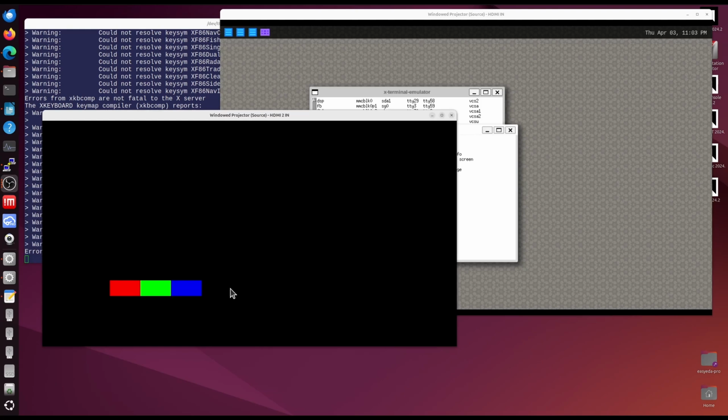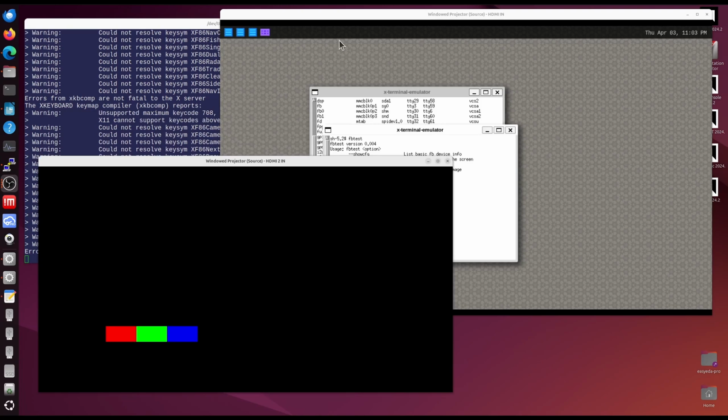And so I'm sure it's a timing thing. It's where's my pixel clock relative to the FIFO, that buffer I've got, or there's something else I haven't quite figured out. And there's some weirdness, and it might come down to a Linux driver, the PetaLinux driver. And I say that because let me do this.